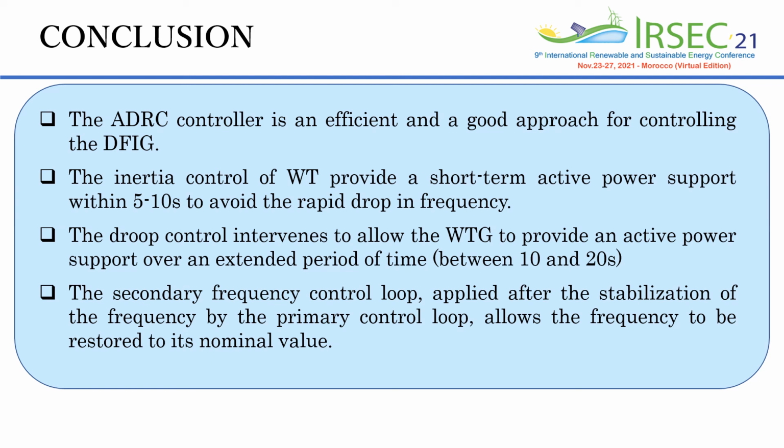The inertia control of the wind turbine provides a short-term active power support in order to avoid the rapid drop in frequency. Also, the droop controller intervenes to allow the wind turbine to provide an active power support over an extended period of time.